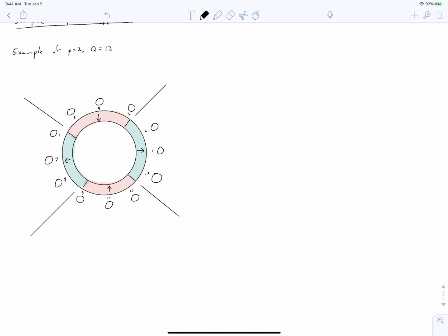And the first thing I want to comment on is that we're going to divide this into poles. You can see I'm labeling this angle out here, which is the pole span of our design. A pole span is 180 degrees electrical, or it is pi by p radians. So it's the angle that a pole of our winding takes up. And we can also talk about a pole span as a linear length, as our book does. It defines this variable tau p, which is equal to our pole span angle times the radius.